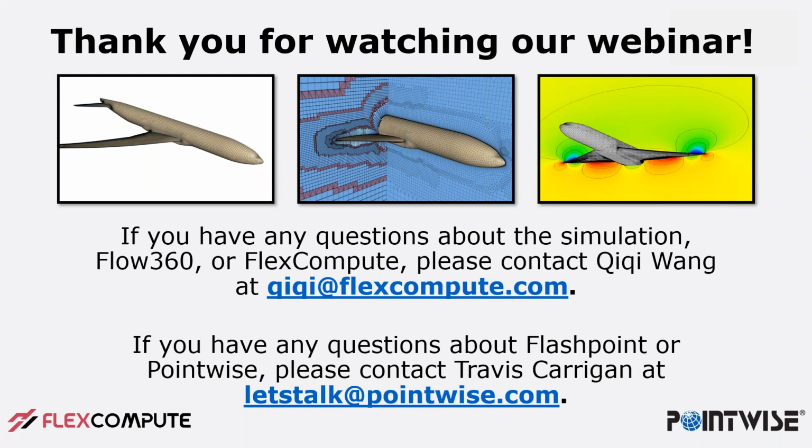The one thing we are missing is rotational periodic boundary conditions, which is often used in turbomachinery simulations. But we have, for example, total pressure, total temperature inlets, static pressure outlets. A lot of the boundary conditions you need for internal flows we already have, but we don't have all of them. Okay. All right. How long does the same analysis take without Flashpoint?